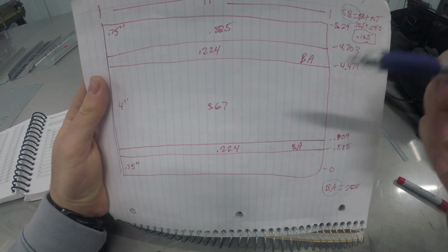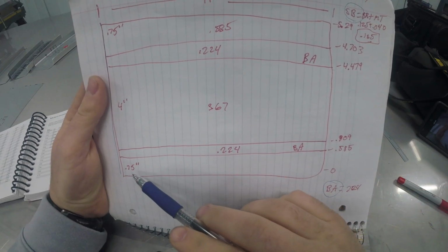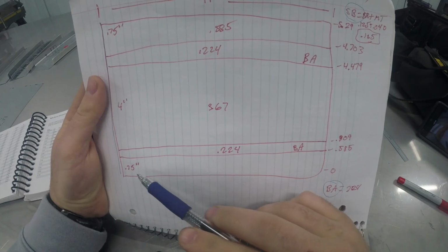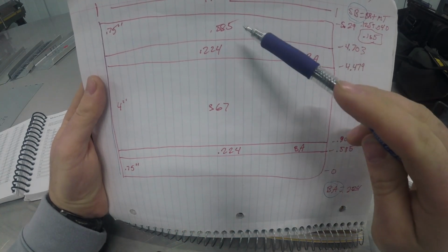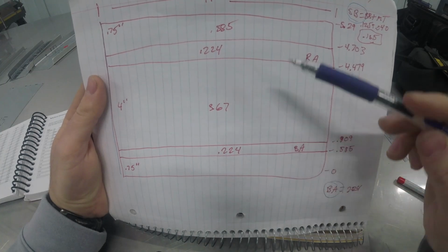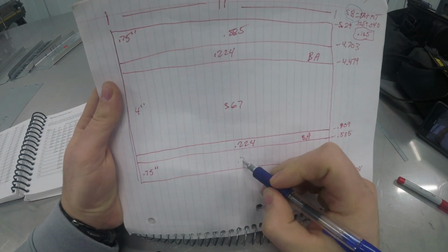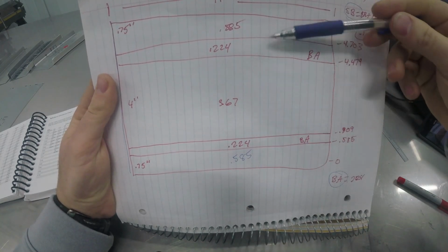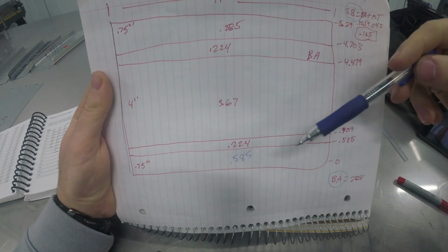So now that we know that, we can go ahead and calculate what our ends need to be. Overall, we want a 0.75 inch length here. So 0.75 minus 0.165 gives us 0.585. We go ahead and write that up here as well. I'll write it down here since I didn't before. Since those are the same lengths, we both want those at 3/4 inch. We go ahead and write that in.